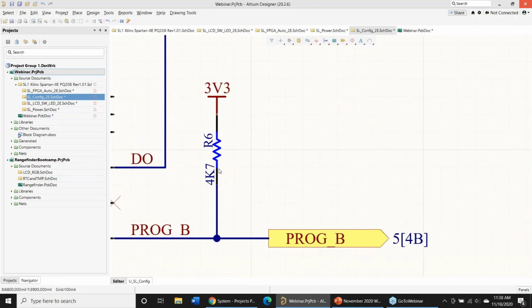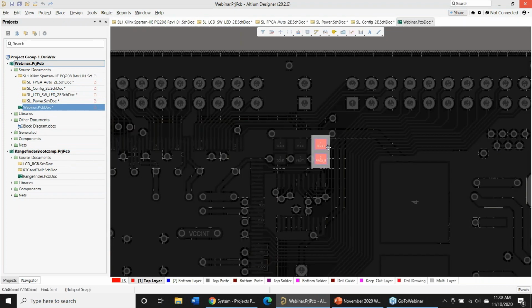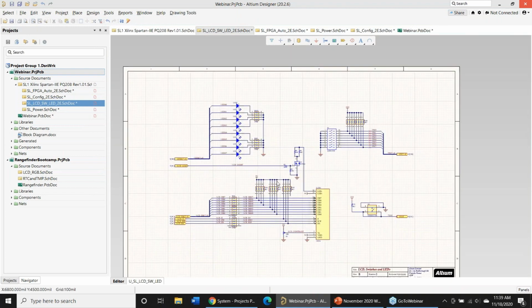If you've ever done this before and you don't know why it's doing this, if you go cross-probe like this and it goes there for a second and then comes back, that's why. It's coming back to this editor. So you just hit the control key and now you're in this editor. So that's cross-probe and cross-select mode.